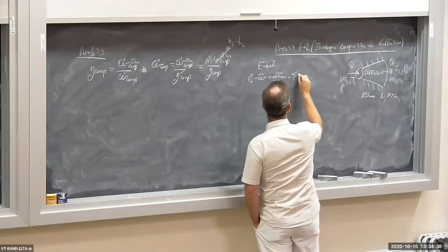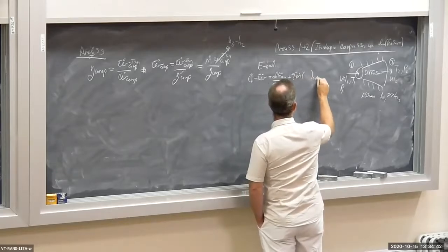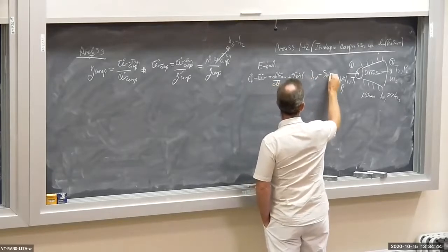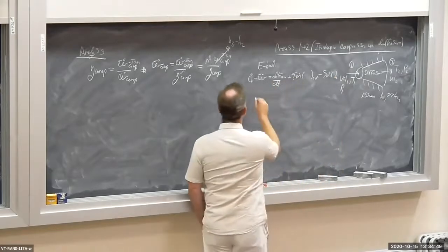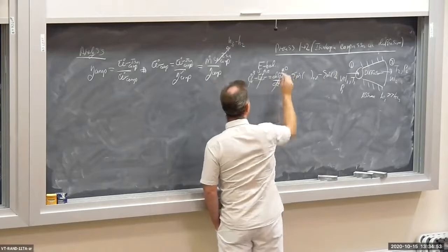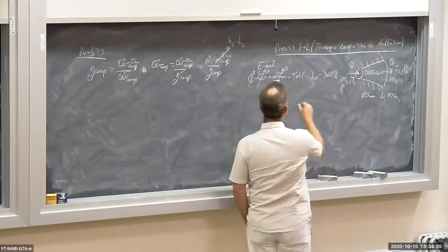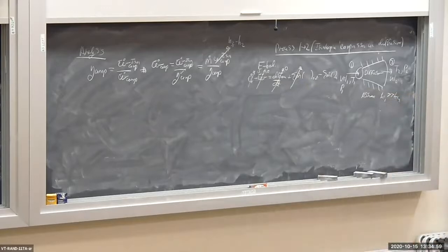And then I have the sum of m dot out minus the sum of m dot in. No heat transfer, no work, steady state. There's no indication this is an unsteady problem. I'm going to neglect changes in height or potential energy.